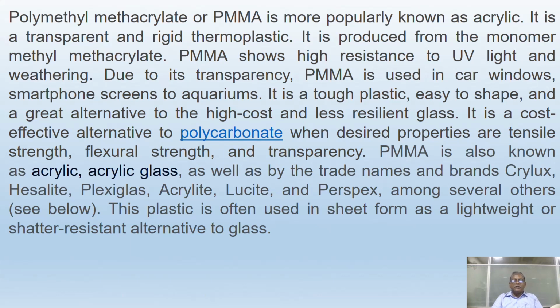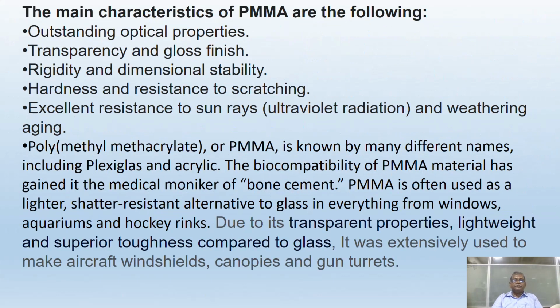PMMA is also known as acrylic or acrylic glass. So, characteristics: outstanding optical properties, transparency and glass finish, rigidity and dimensional stability, hardness and resistance to scratching.